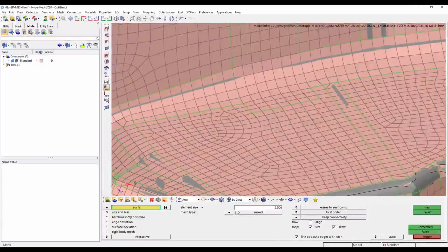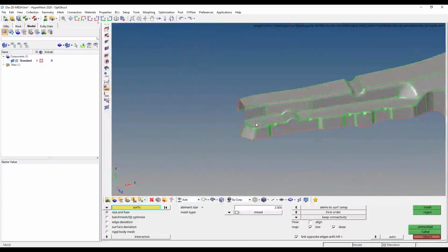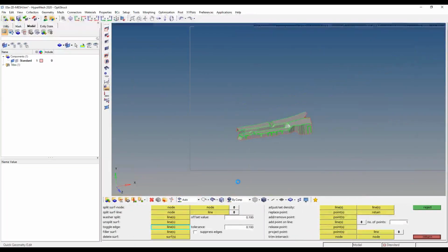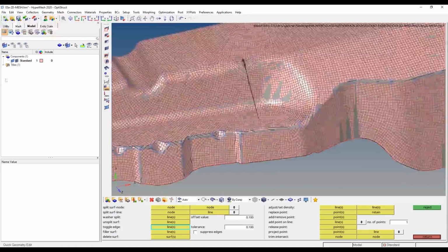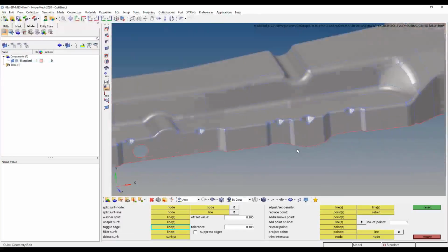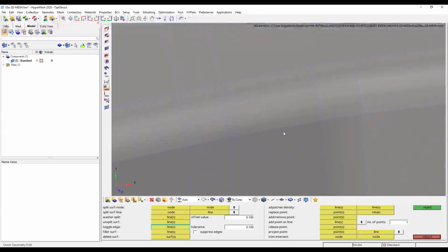So before we take a break here, I'm seeing a question that came in a few moments ago from Cedar. Will it make sense to remove all the edges for a smooth mesh? No, that's something you'd actually want to stay away from, Cedar. The reason why is, let's look at that together here. If you turned off all of your edges, like I've done here, so the only edges I've kept on my part are the exterior boundaries of the part, that's a dangerous thing to get into, because now I've lost definition on where this fillet starts and where it stops.